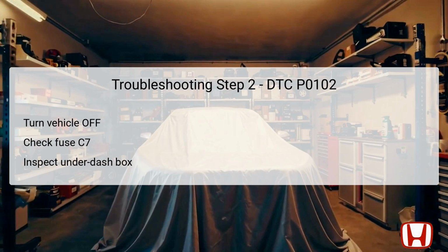Additionally, if the fuse continues to blow after replacement, further investigation is warranted for potential short circuits in the wiring associated with the IG1 ACG circuit or the EGR circuit between the PCM and the EGR valve. Detecting electrical faults at this stage is crucial for ensuring that the MAF sensor operates effectively.